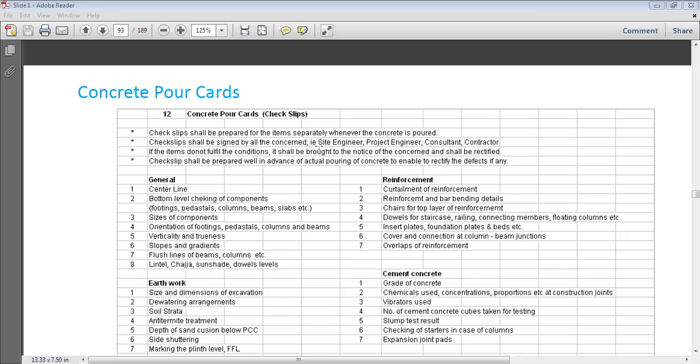Okay, so on that day we had to go there. Then we arranged proper side shuttering. We once again revised it, proper side shuttering, so that we protected our site. Otherwise, that will come to your penalty. That is your fault if you don't provide a proper side shuttering arrangement for your excavated portion.